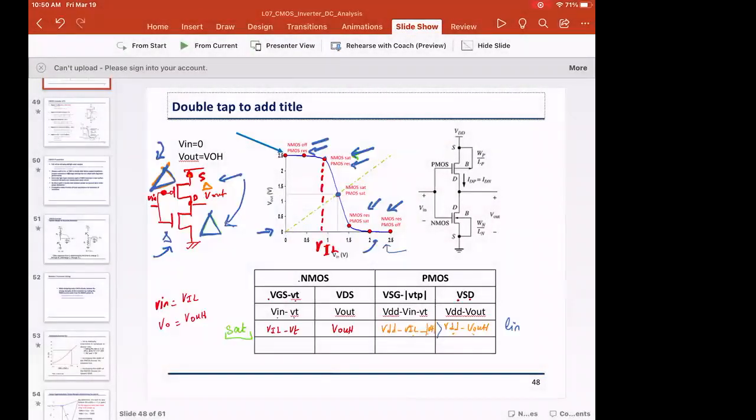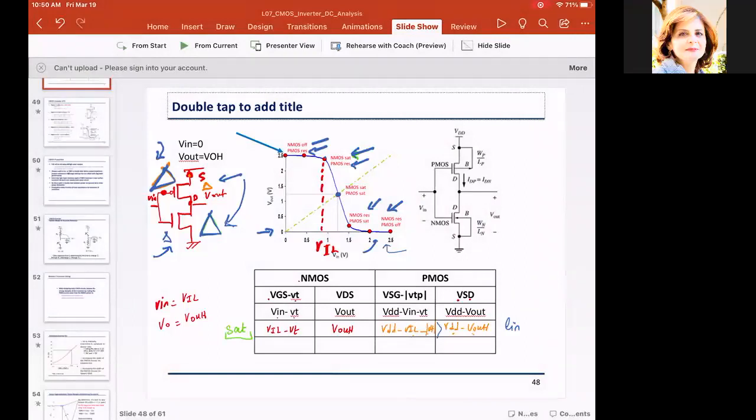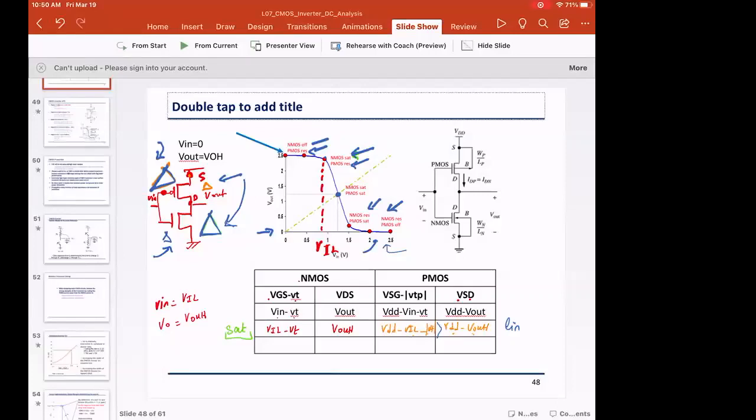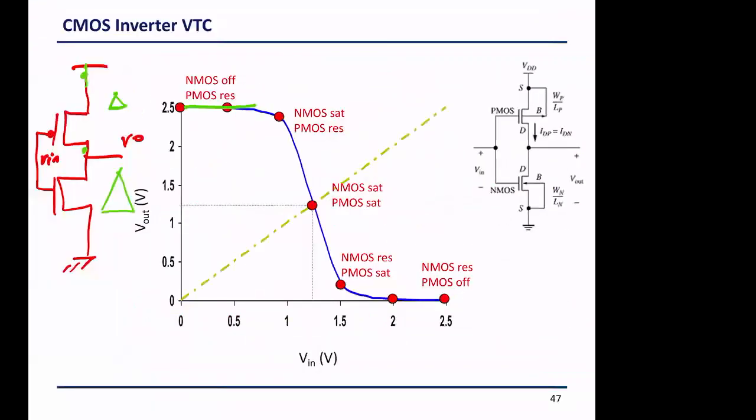Thank you. In the pseudo-NMOS implementation, why is VOL assumed to be low if we have a resistance above the output node and we have the resistance below? Like, why did we assume the voltage division over the resistances to be low? Okay, because the transistor will have a small resistor value.